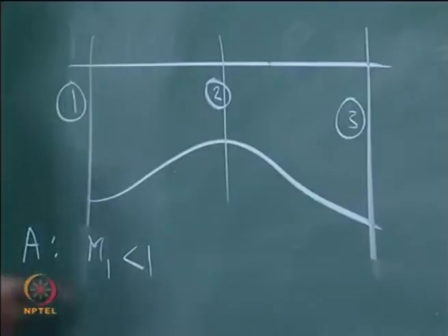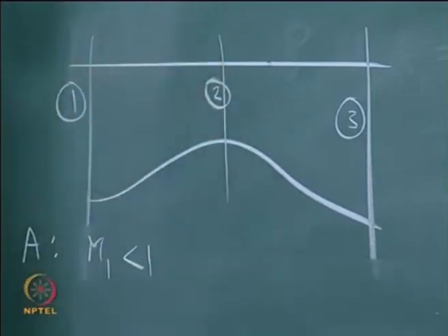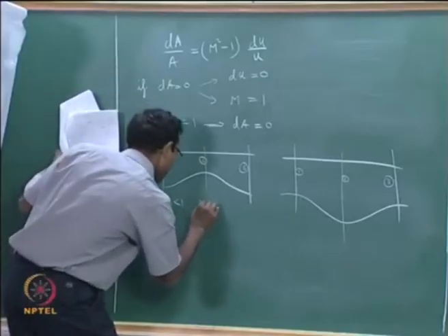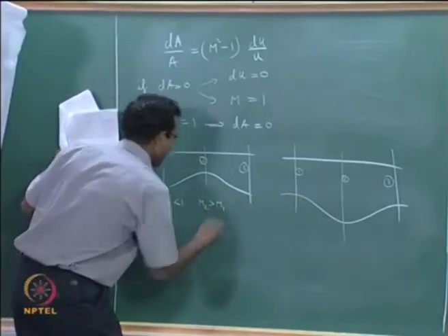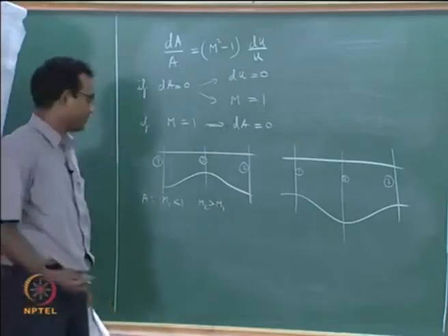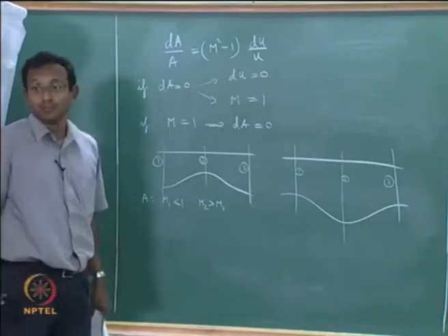Okay. Because subsonic flow, we already wrote the table, subsonic flow, this will accelerate. Okay. So I can tell that M2 greater than M1. Now what all can happen? Let us pick a case where M2 is greater than M1 and goes to Mach 1, let us assume.